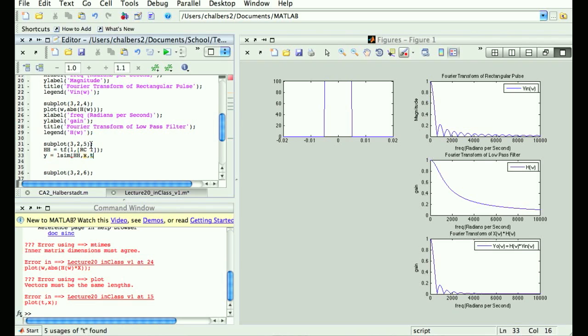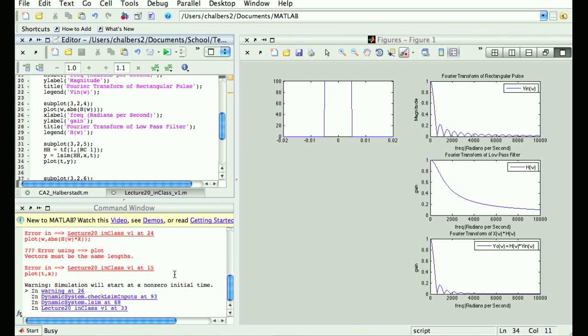Okay, now before you start applauding, which I know is your natural response at a time like this, I just want to discuss if this makes sense. So we talked before about how if you put a step input, you get a rising charge, and that's exactly what we're seeing here, right? And then when you take the square pulse away, you've got a decaying discharge. Is that right? Good, and that's what we're seeing.